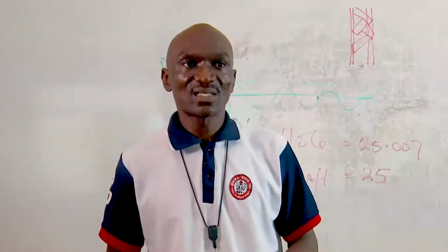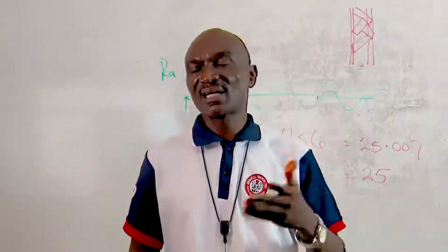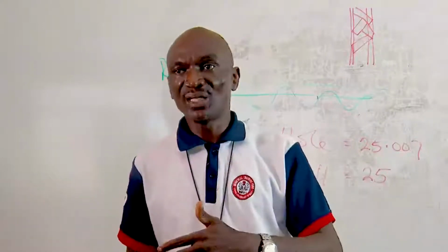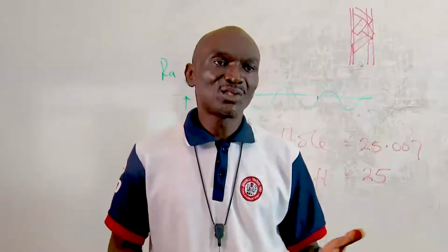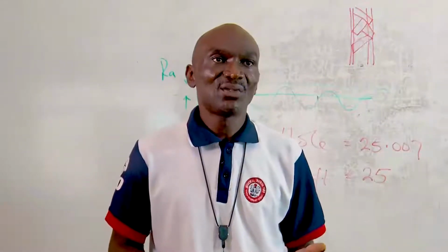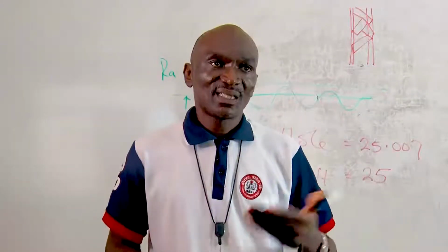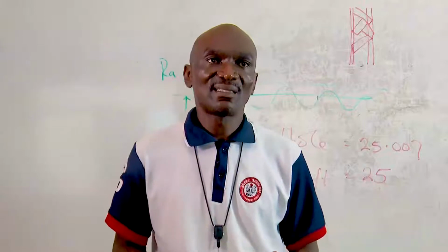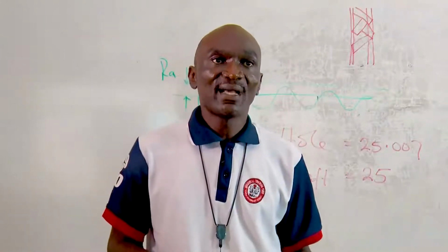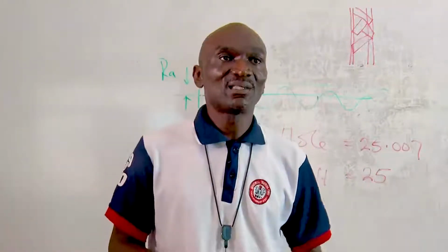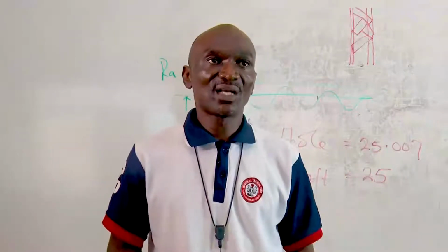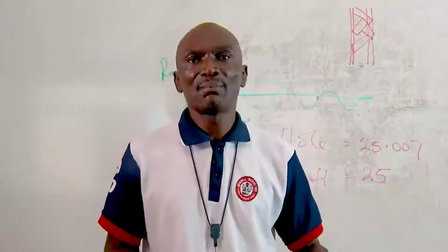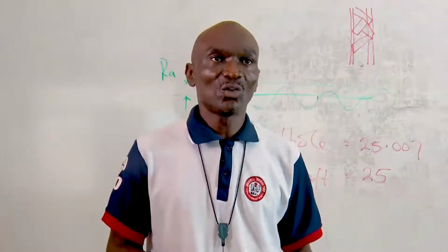We looked at factors like the type of loading, which could be impact, static, dynamic. We looked at the type of motion, it could be sliding or rolling. We looked at factors like temperature, lubrication, and other factors that could affect the wear rate. Then we looked at types of wear and what causes each particular type of wear. Here we looked at frictional wear as a result of heat, erosive wear, cavitation, impact wear, and corrosion.